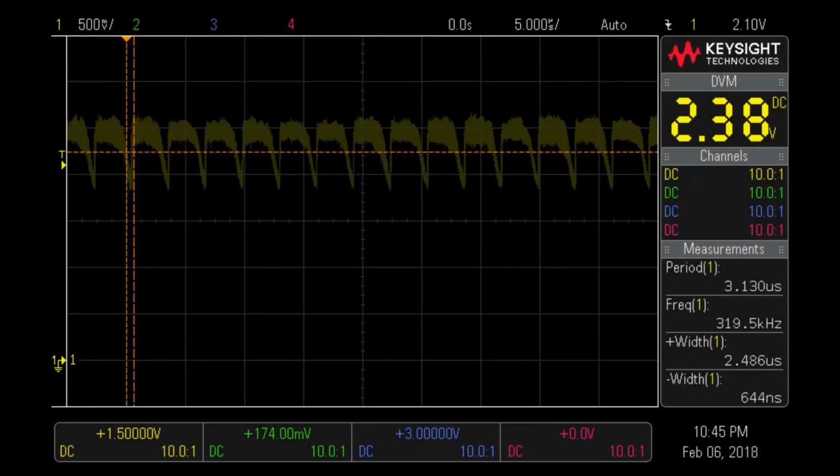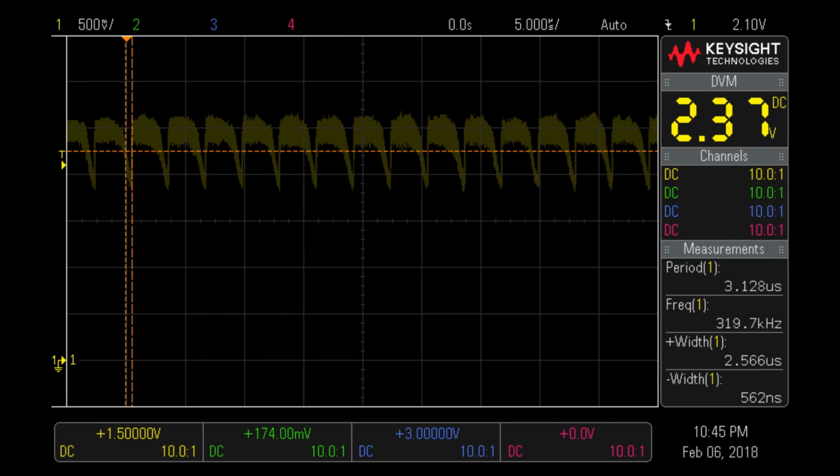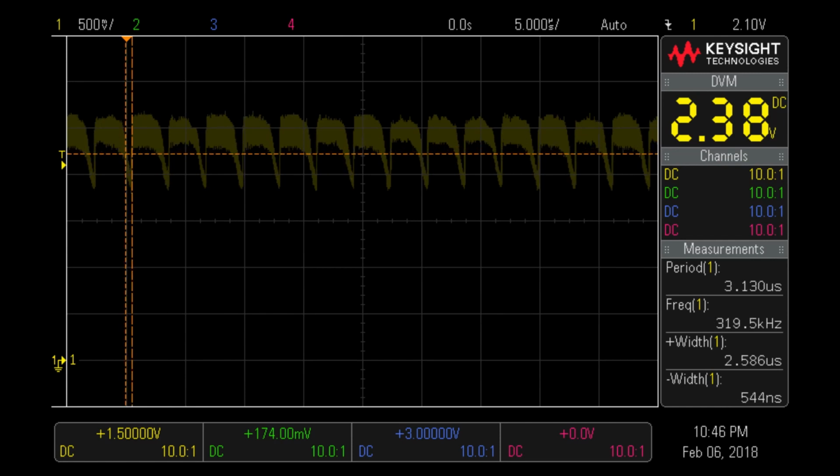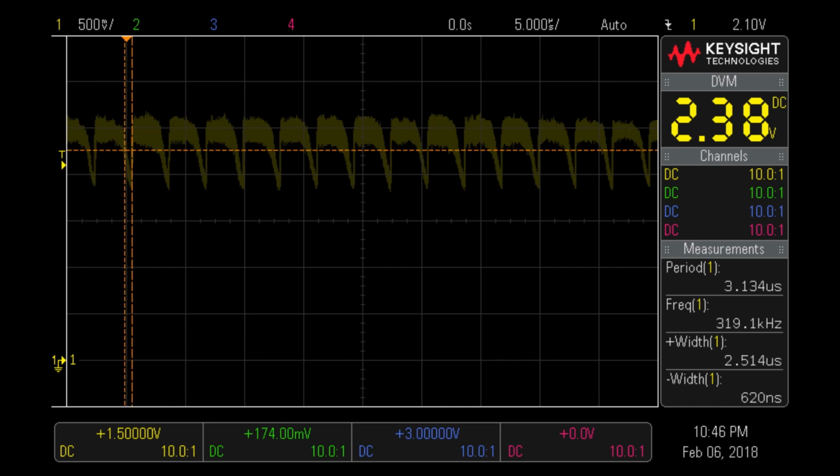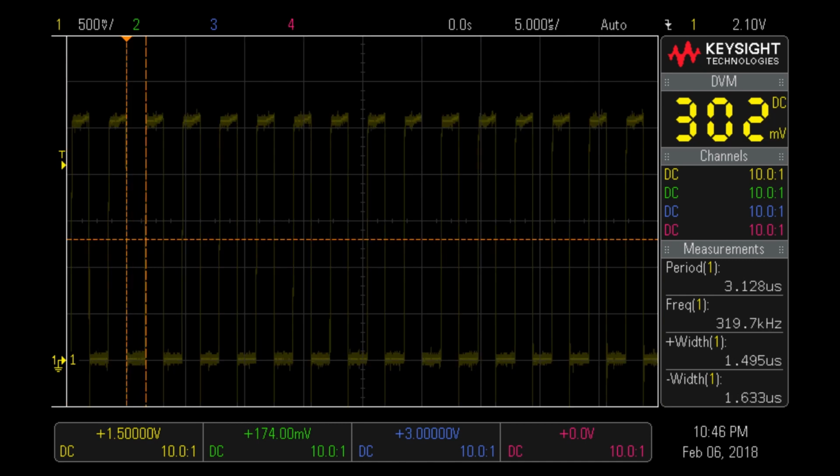Looking at the scope, we get about 320 kilohertz, but we get this very asymmetric waveform. Moving the scope probe from the power rail of the LEDs to the signal directly from the STM32, we see more like what we would have expected, which either points to the switching characteristics of the transistor or potentially some capacitance. Given that the LED chain worked correctly with the other controller, I'd suspect that this points more at the switching characteristics of our circuit.